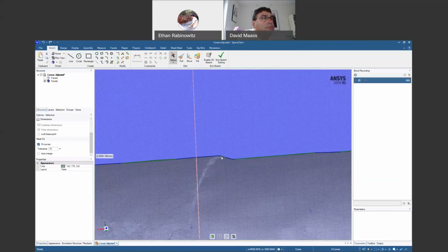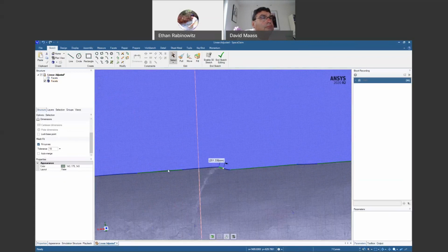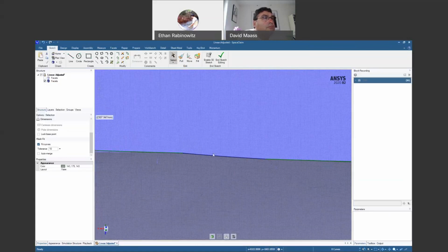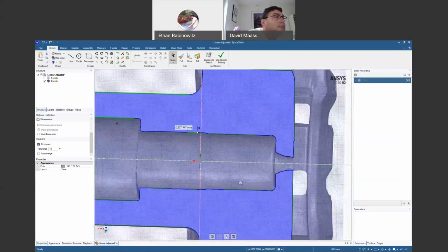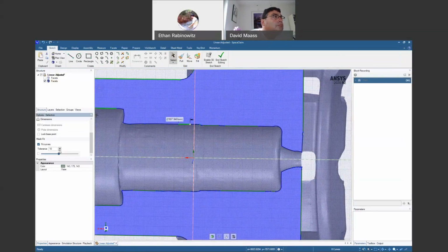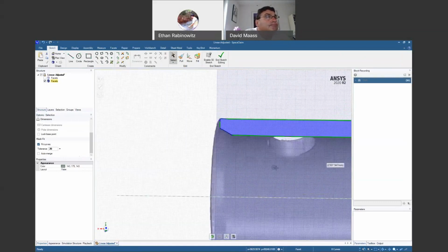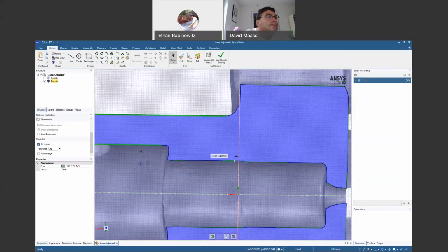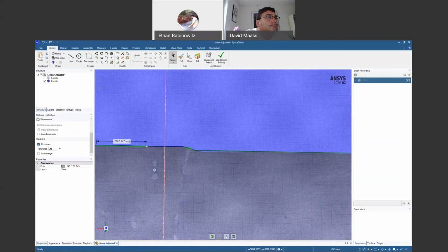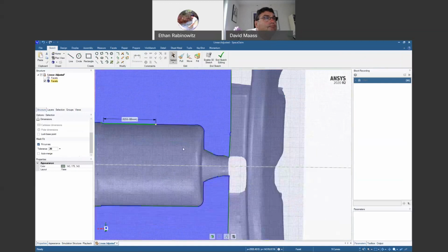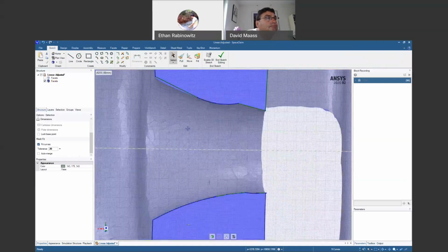Here we can see a little step in there, and that actually looks like it's at a good angle, so I'll grab that and that. Here I have to decide, is it really two diameters? One thing I can do is adjust the tolerance on this curve fitting. If I turn it up a little bit, you'll notice it's a more relaxed tolerance. Usually we'll get longer lines in certain places, giving us more of an indication. So I think we're looking at it being just one here. And here I'm just holding down the control key as I select these.